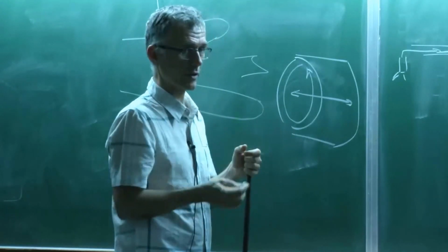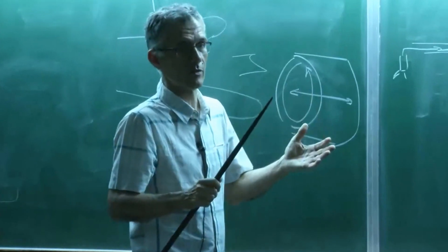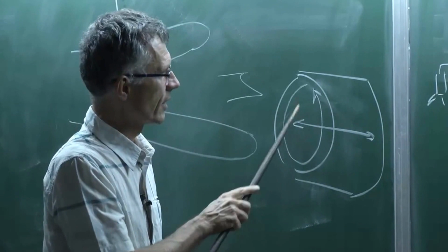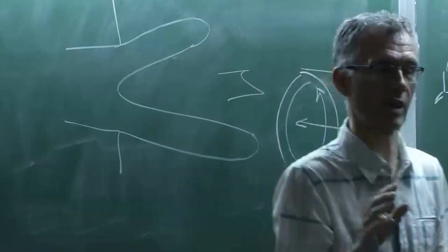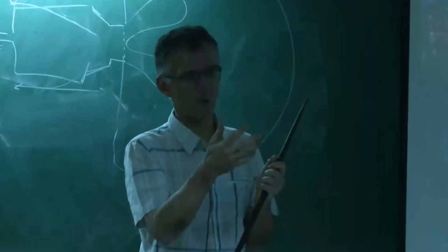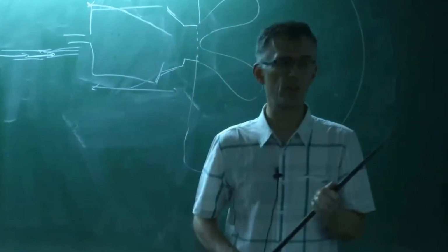So if you see a frequency, it can be a longitudinal mode or a transverse mode or an azimuthal mode. It's difficult to know as long as you don't have the structure. So if you know just the frequency and the frequency only, you're stuck. You need more sensors. You need multiple microphones, but just the frequency is not enough.